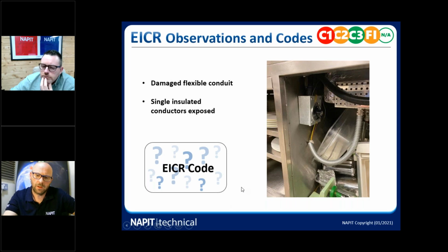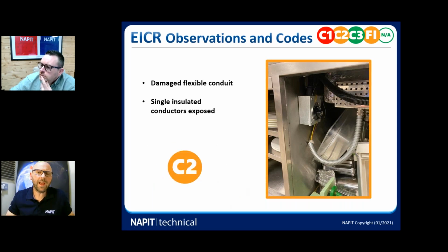Okay. Yeah, it's got the potential for danger. It's not currently danger present, but it's got that potential for danger. And remember, when you give a frequency for an inspection, depending what you've given it, it may be a year, 3 years, 5 years, whatever, that's a long time to wait until it next gets inspected. So something like this, it's satisfactory. It's just deciding between the 1 and the 2 that inspectors need to make the decision. And in this case, it's got the potential for danger.